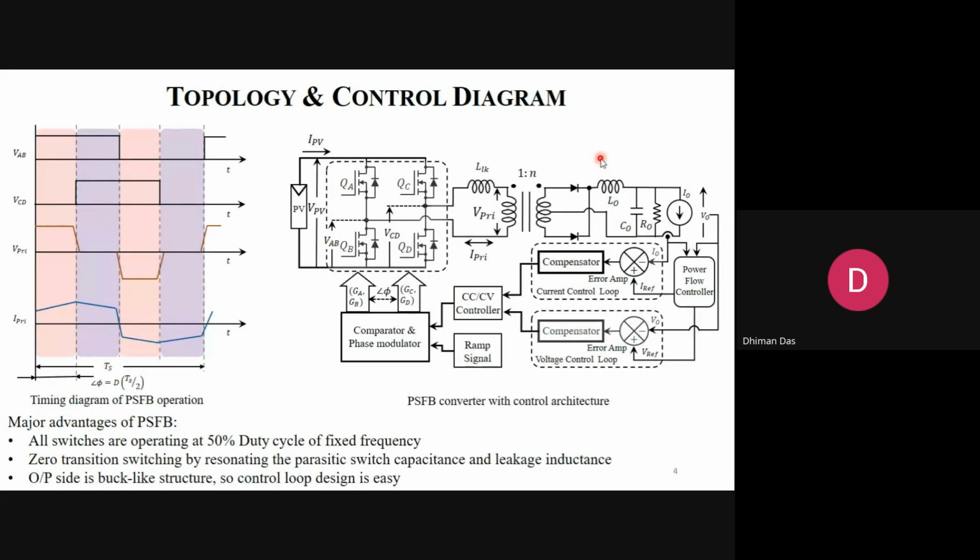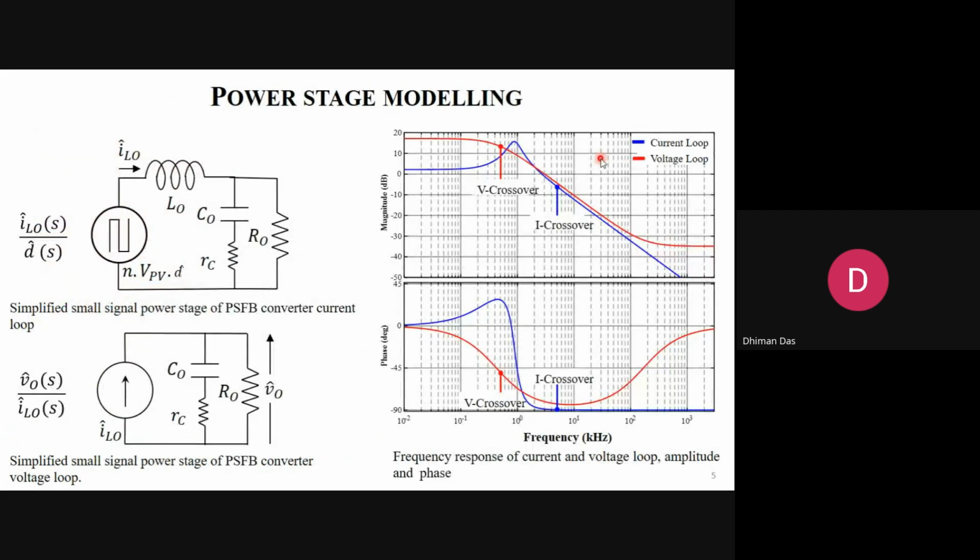When you rectify any signal, it becomes double frequency. So this is similar to a buck converter. When you simplify the whole converter, it looks like a buck converter. Here, this is a pulsating voltage having a fixed duty, and the phase shift angle is converted into duty, and this is the normal LC filter, and this is the load.